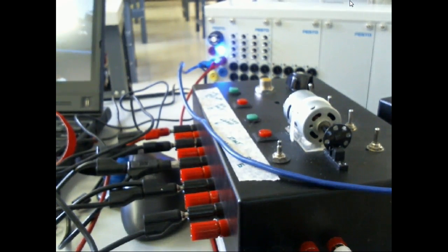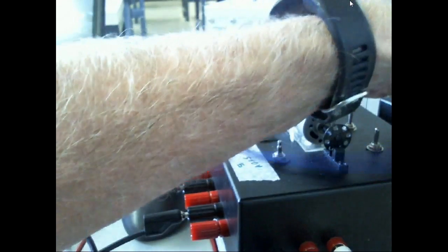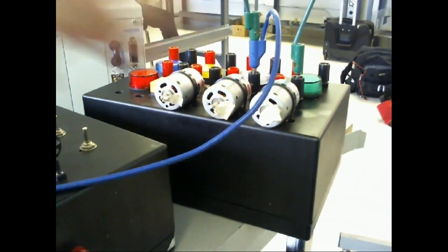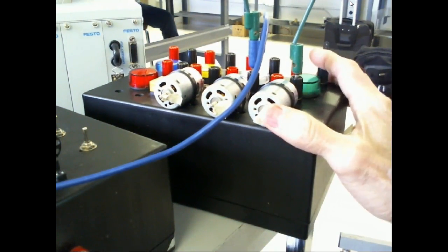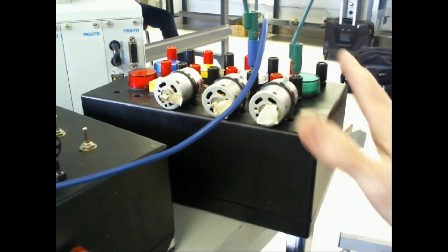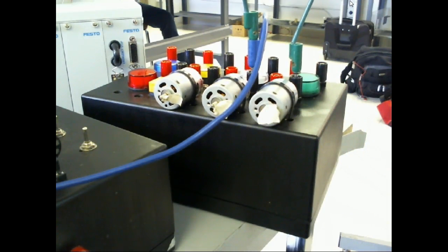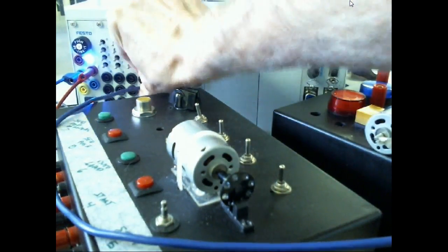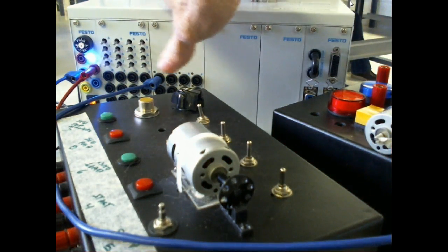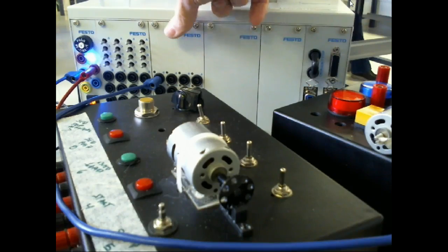And then I would take my outputs, which are set up to source. See what I'm doing? Okay, so what I've done is I brought the minus over here, and I have that jumped over here. So I've set up these as sinking, right? And my outputs are set up to do what? Source. Makes sense? Everybody okay so far? And then these outputs over here are designed to source, so I can just come over here and hook this up. Now, if you were wiring directly to the PLC, you would be wiring these up here, right? You understand?